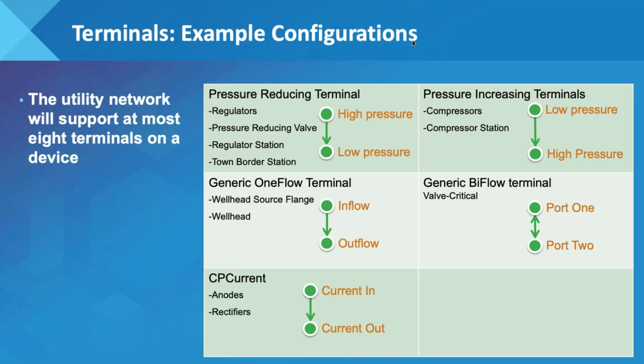That doesn't really stop at the product flow as well. We were using these devices to actually model and map the CP, or the cathodic protection, along these pipelines. So not only can I see all the devices that are connected together by pressure, I can see all the devices that are electrically connected together. So I can connect my rectifiers, my anodes, my test leads, my insulated flanges, and be able to look at my system from a CP perspective as well as a pressure perspective.